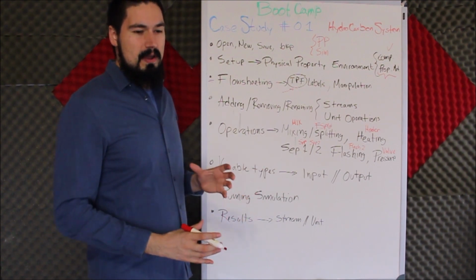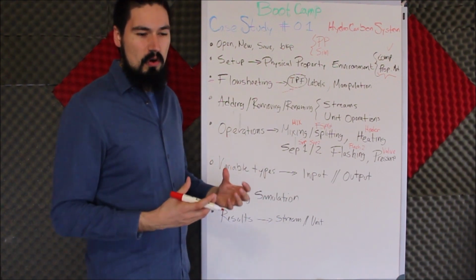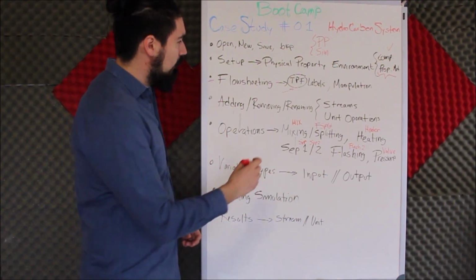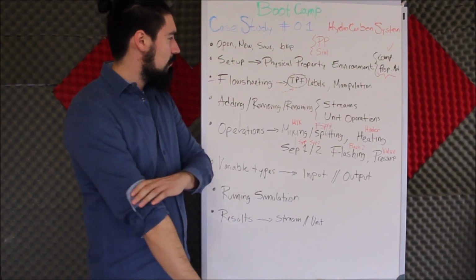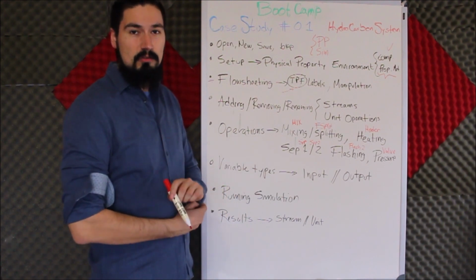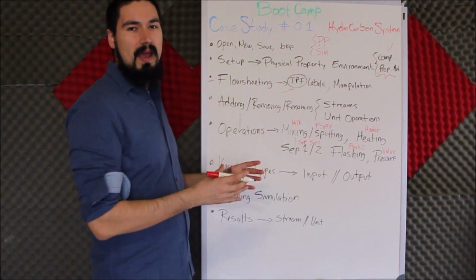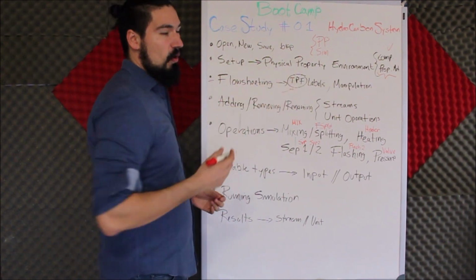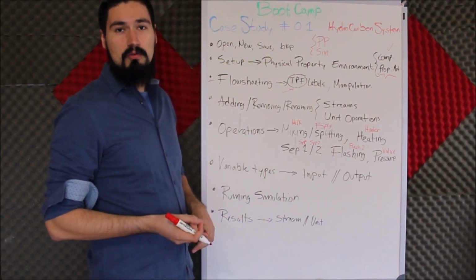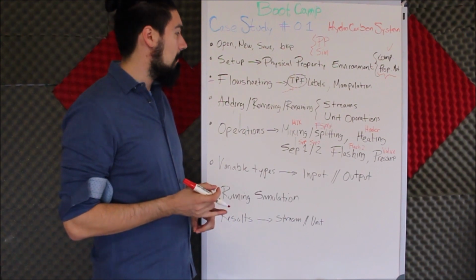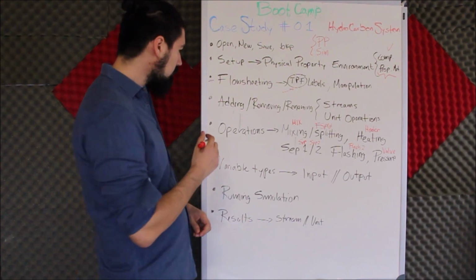How can you move around or manipulate the flowsheet more easily in order to understand what's happening with the simulation. We're going to be adding these labels: temperature, pressure, flow, vapor fractions. You can also even add heat duties, work duties. Whatever type of simulation you're doing, you should always add what is convenient for you. For instance, flow: if you're working with moles, add flows of moles. If you're working maybe with volume, you're going to be interested in volumetric units, or if you're working with mass, add mass units.